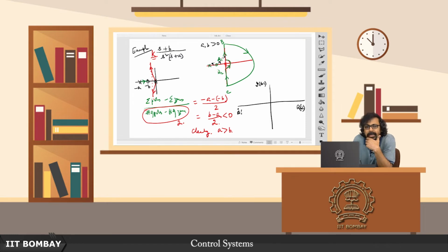0, they cancel each other's effect at the point B, because even the pole contributes a 90 degree, right. So the 3 poles, all 3 of them contribute 90 degrees, so minus 90 into 3, that is minus 270, and the 0 contributes a plus 90, yeah. So it is effectively minus 180 degrees. So it is of course still a 0, but with a minus 180 degrees.